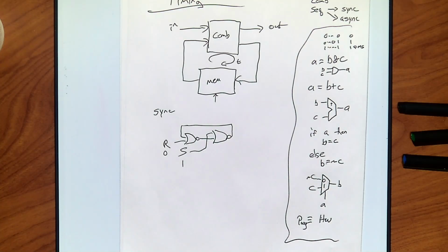Yeah, things are unstable for a bit. So I want to prevent that. So I'm going to want a period where set and reset, my inputs, cannot change within that clock cycle. Because otherwise, you can imagine what if I go to 0, 1, right? So I'm starting to set the thing, and then set turns off. Well, I started to transition and now it turned off. Does it make it up and latch or does it drop back down? Well, it depends on how far you progress. Well, how far do you progress? Well, that depends on how hot it is. Right, in the logic family.